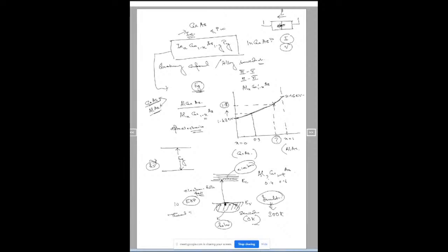Why do we need to understand this? Because we will have an additional generation now that light comes into the picture. Here, in a purely electronic device, you see that thermally generated carriers are there. Now I will apply an electric field and see what is happening. But in an optoelectronic device, in addition to these thermally generated carriers, we'll have some additional carriers which are generated by light.